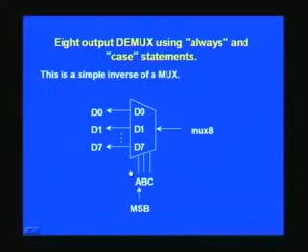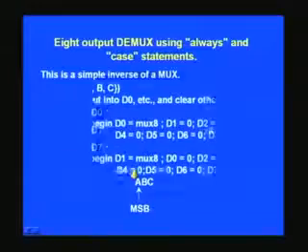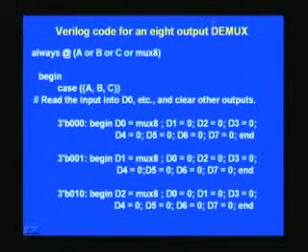And this appears to be a little more complicated because this is once again using the same always statement, and whatever inputs are being used here, note that mux 8 is also an input here, and you have to list all of them. And notice that it is only OR, no AND is valid here, right?